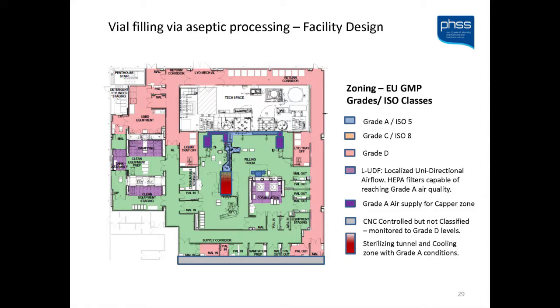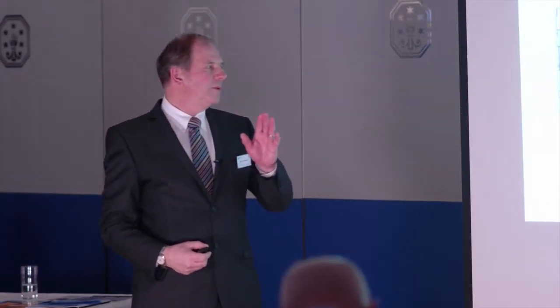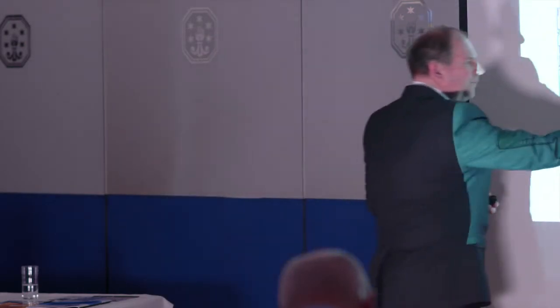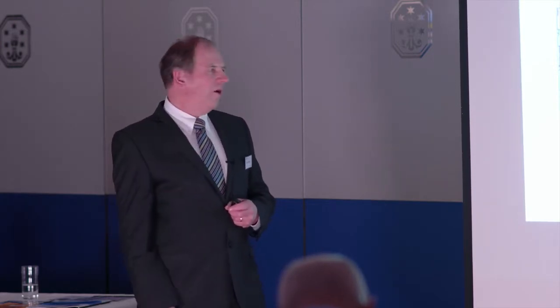Now, in fill-finish applications in the real world, we need to look at the sections that are VHP'd and those that may be just manually disinfected, and how we control that between them. Where the autoclave is, how we get microbiological plates in and out of these lines for a campaign. Here we have a solution of a rapid decon 30-minute cycle with VHP, just to do the outside of agar plates.